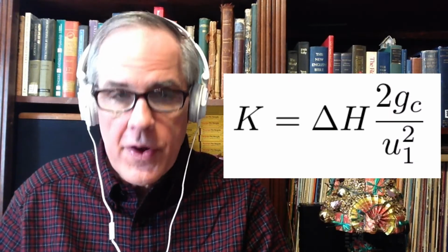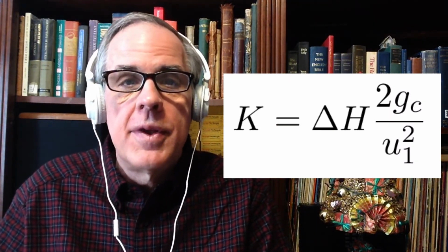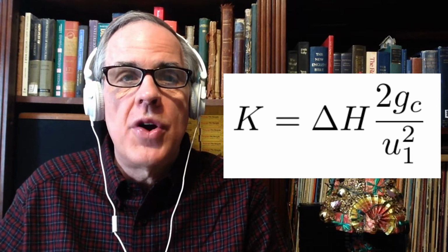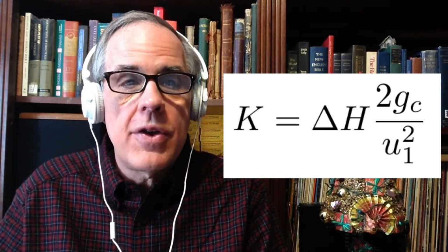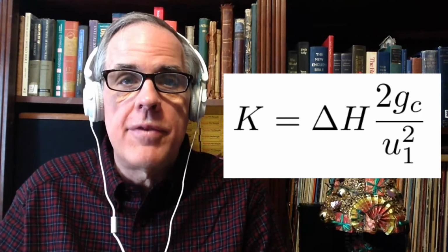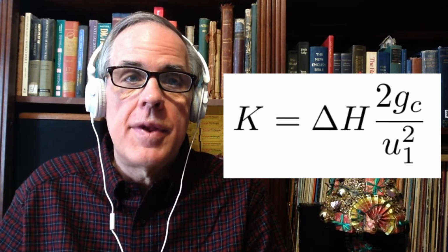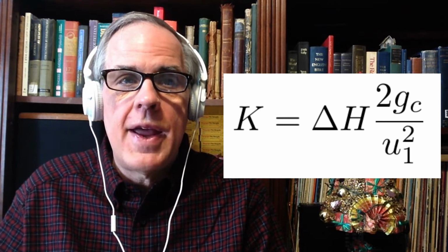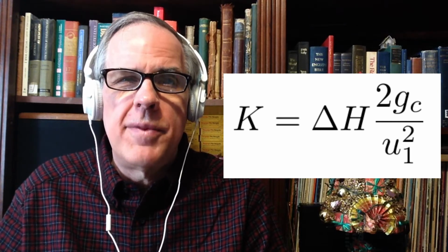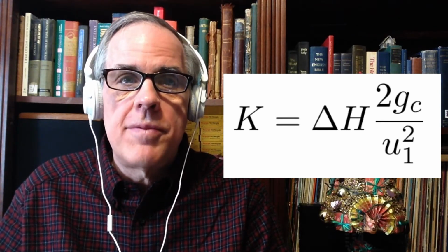So we basically set up the so-called flow coefficients, the K values, where we don't need to know that. The K values can be above 1, and very frequently are for high loss devices. In this experiment, and again, I explained the math in some detail, I said that you could actually relate K values to discharge coefficients if you know that internal area.